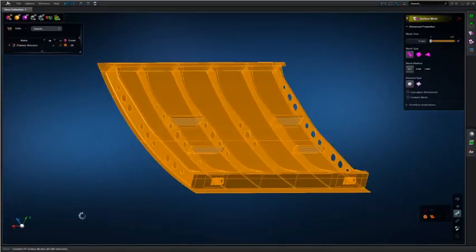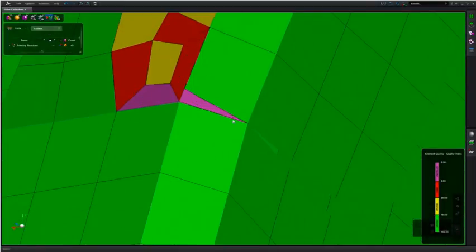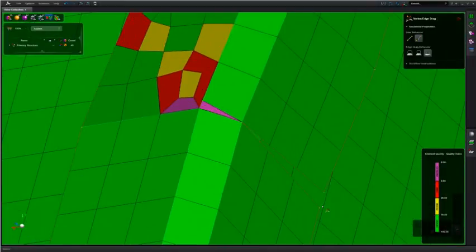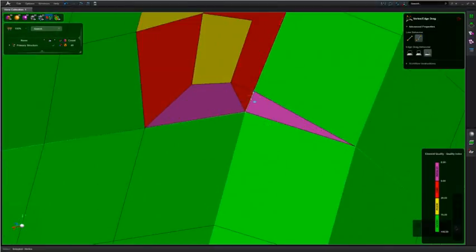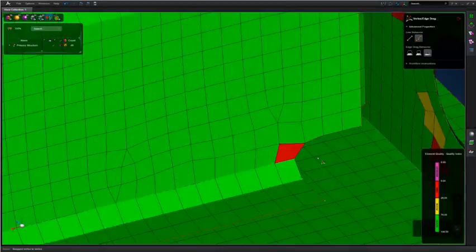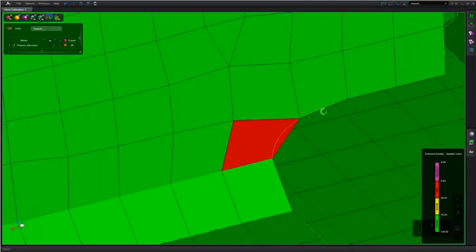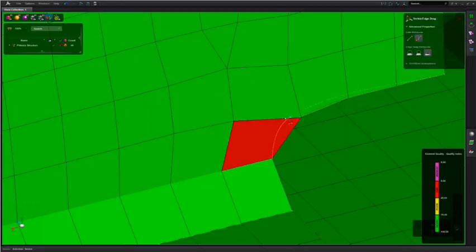Let's go ahead and mesh this model. A look at the mesh quality reveals some poorly shaped elements. No worries, I'll simply select the geometry and move it until the quality of the mesh is improved. And we can do this because of the CAE specific direct modeling and meshing technology available in the application. With each change in the geometry, the mesh is regenerated.